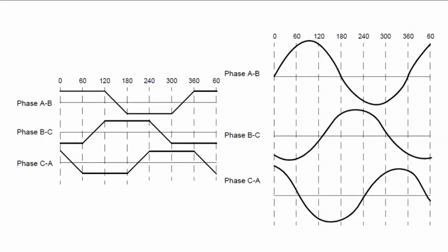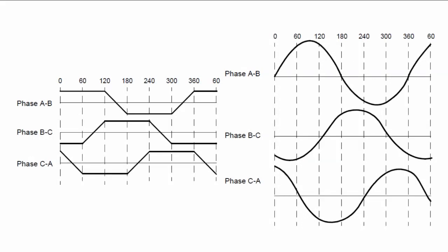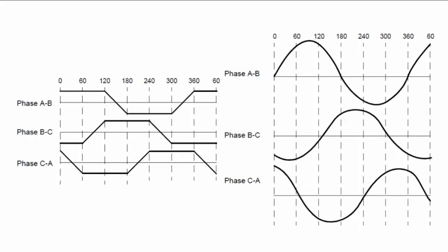What is the slip? We have two types: synchronous motor and asynchronous motor. Why can we call it synchronous? Why can we call it asynchronous? In your motor conversion course, maybe you can remember. Asynchronous motors have a slip: the magnetic rotating field speed and the mechanical rotating speed are not the same.